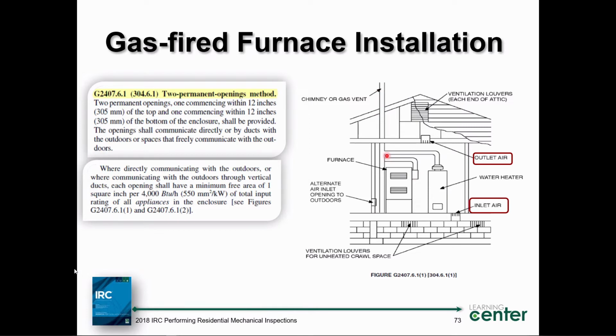In other words, you have a choice. You could use outside air, you can use inside air, but I caution you to use inside air because of the way we build our homes today. Maybe you can help me. Have our energy codes gotten stricter and stricter every edition? Absolutely. They have, haven't they? We're tightening up our houses. Our houses do not breathe like they used to.